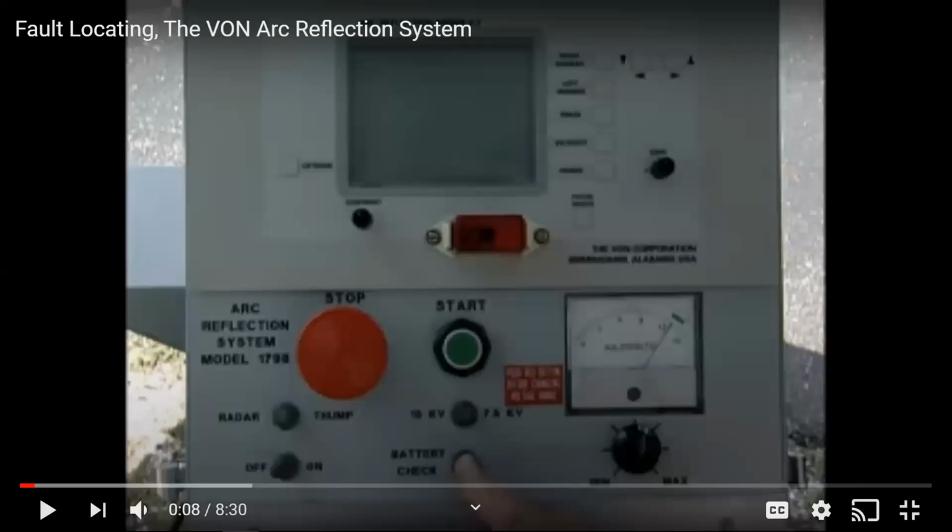All right, the piece of equipment we're going to use here is what's called a Vaughan thumper. Vaughan is the name of the company, and a thumper is exactly what it means to say. It charges up the cable to a certain point, and then injects real high voltage on it, and the cable thumps in the ground where the fault is at. So here's how it operates.